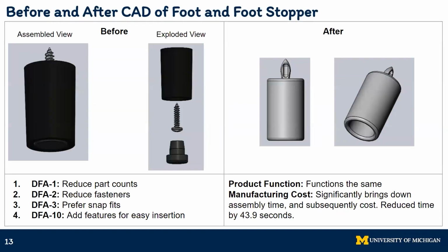On the next slide you can see, we similarly combine parts of the foot to one part that will make for easy insertion by making it a snap fit into the existing toaster design. Subsequently, we estimate that this will reduce assembly time by about 45 seconds.